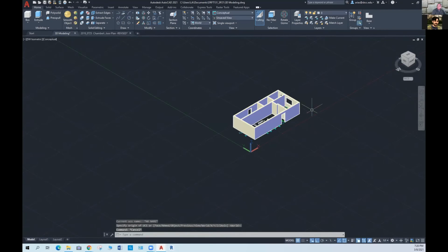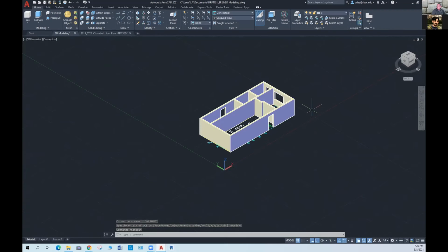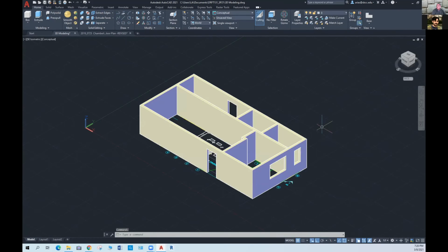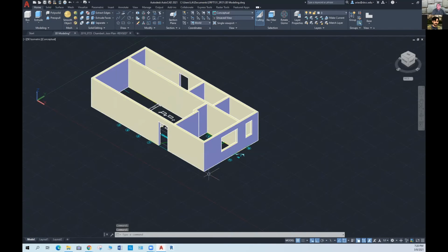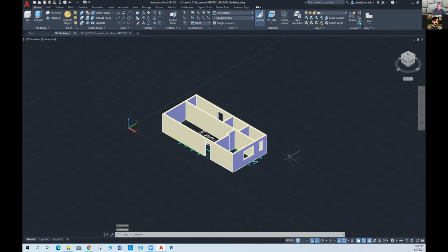And so if I want to be at 0, 0, then I need to actually locate my 0, 0 right there. And there are a couple of ways of doing that, but probably the best one is to actually just rotate this object and make it be there. Or locate the UCS icon to be at that origin as well. Let me rotate the object.